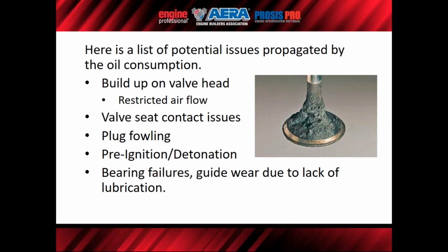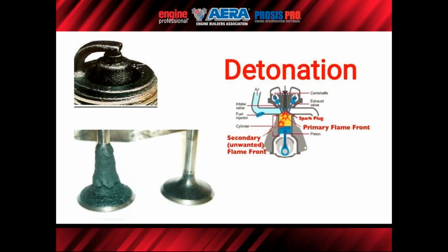Again, we're changing our fuel source, so pre-ignition or detonation. Bearing failures and valve guide wear due to lack of lubrication where we expect it to be. So here's just a couple more images. Again, detonation, pre-ignition. For my detonation, I have a secondary unwanted flame front.